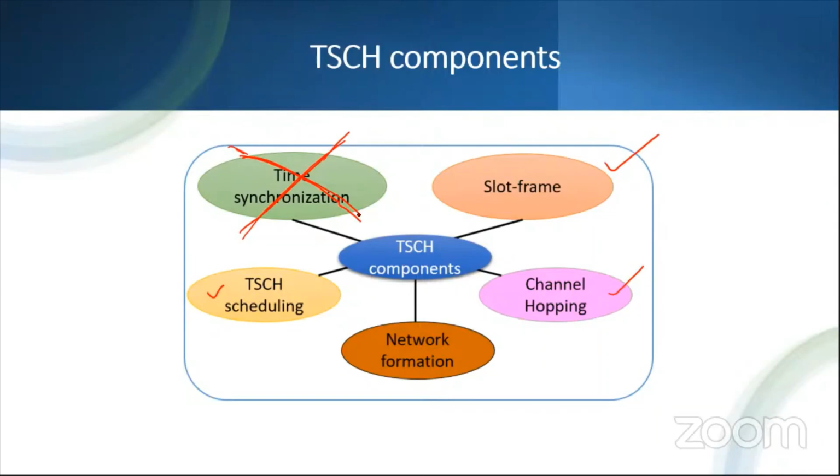Sure. The whole idea of system on chip is that several components of the hardware get integrated into one single silicon. You have radio coming into silicon. You have power supply coming into silicon. You have flash memory coming into silicon. RAM is in the same silicon. CPU is out there. All of this, right? Including nowadays the balun of the RF transmitter is also in silicon. So if you want to study SoC, you have to study each one of these components independently and then look at the SoC in a holistic manner.